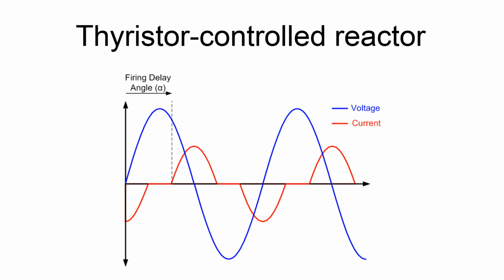Another device which used to be used for this purpose is a magnetically controlled reactor, MCR, a type of magnetic amplifier otherwise known as a transductor. In parallel with the series-connected reactance and thyristor valve, there may also be a capacitor bank, which may be permanently connected or which may use mechanical or thyristor switching. The combination is called a static VAR compensator.